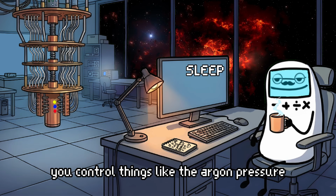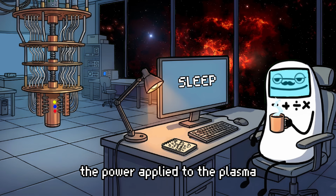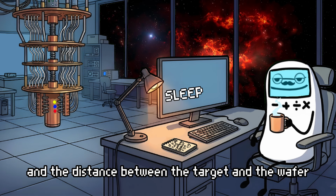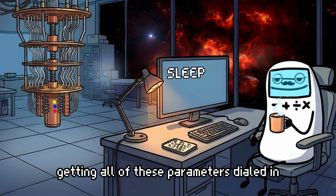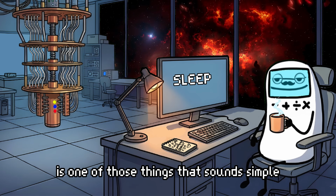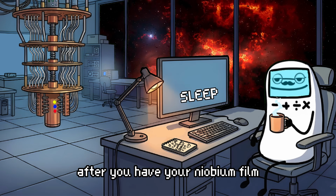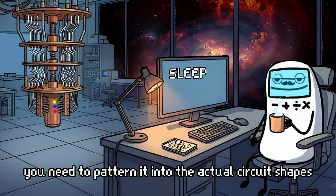You control things like the argon pressure, the power applied to the plasma, the temperature of the substrate during deposition, and the distance between the target and the wafer. Getting all of these parameters dialed in is one of those things that sounds simple but takes months of experimentation and practice. After you have your niobium film, you need to pattern it into the actual circuit shapes.